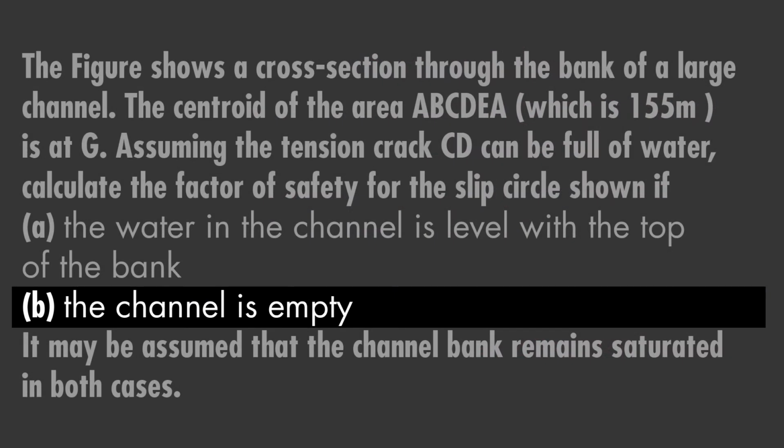Part B of this question asks you to calculate the factor of safety for the same slope when the channel is empty. So when you have a slope for this kind of a channel, it is very important to calculate the factor of safety considering both scenarios, when the channel is fully filled and also when the channel is empty.